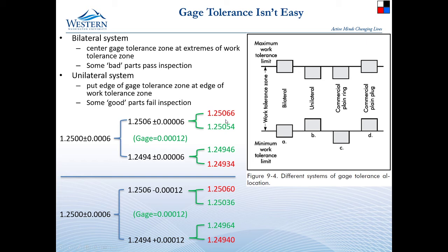If you don't actually want parts to be within that tolerance zone, or it doesn't bother you, why would you allow that to happen? For some things, you can see for rings, they will be inside on both the large and the small side, and for plugs, they will be inside on the small side and bilateral on the large side. The reason that this happens somewhat is because of wear.